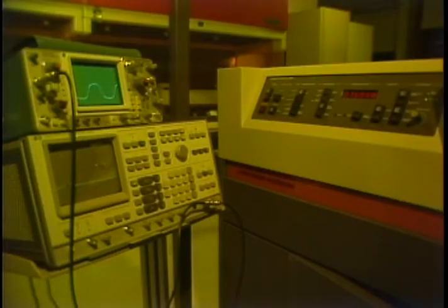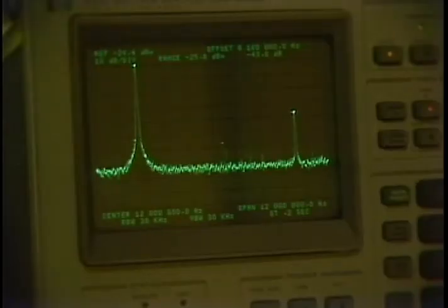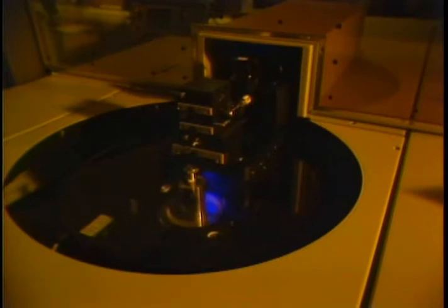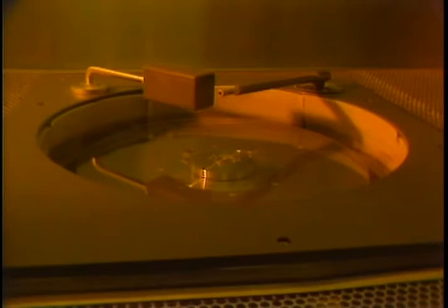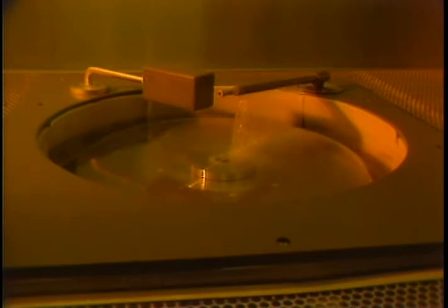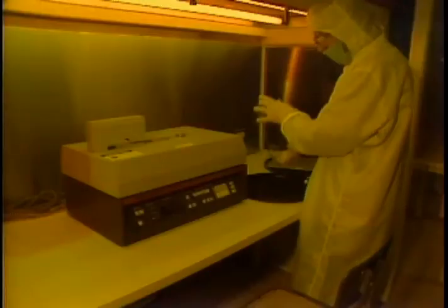A laser beam, focused to a half-micron point, is pulse modulated by the combined video and audio signals sent from your master tape. Exposing the master disk is done in real time. That is, 1 minute of program takes 1 minute to record. 200 million pits are recorded in each square inch. The length of the video disc track stretched out would equal nearly 27 miles. The laser causes a photochemical reaction in the resist layer on the master. When the exposure is finished, the disc is developed. This cleans out the billions of microscopic pits which are arranged in a spiral configuration that begins at the inner radius. The master is then inspected before baking to harden the surface.